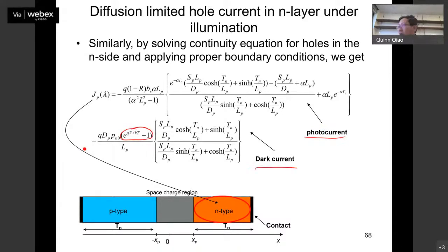The second reason is that this term is not related to the flux. It's kind of constant and only depends on the applied bias. That's a diode property, a diode signature. And then the first part you have BS here, the same as what we discussed before. That's why it's related to the light. You have higher light intensity, higher photon flux, and they have what? Higher current.